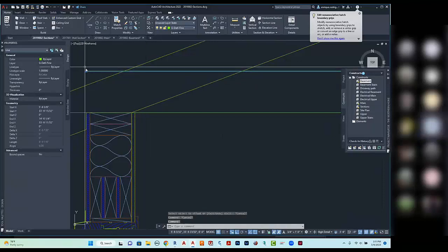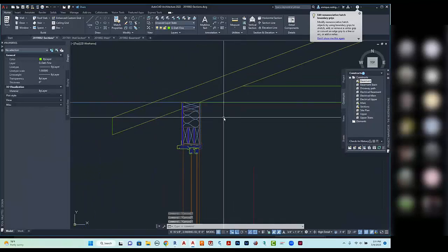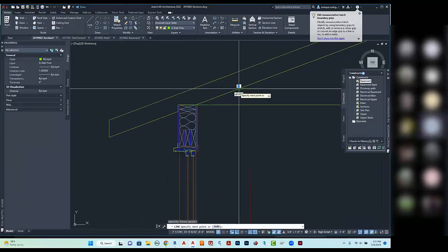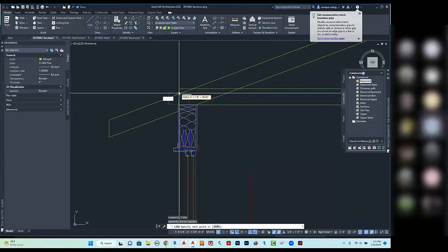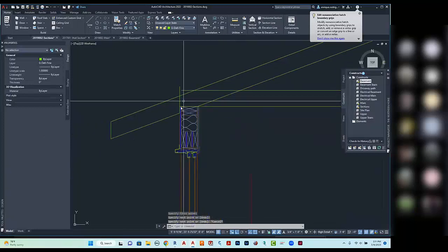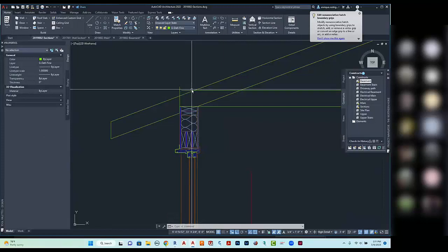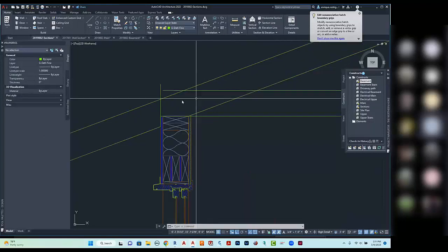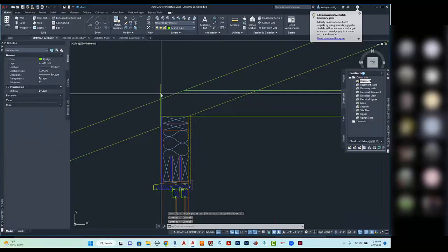And I'm going to bring this guy back to that intersection. I can remove my guideline at this point. I'm going to draw a shorter line here. And I'm going to draw a vertical line here, which I'm going to trim off also. Notice if we did not trim the top of that ceiling rafter, the corner here in a triangular piece, that means it would stick up through the roof. We don't want that to happen. I can either trim this piece off or bring it back to the intersection point.